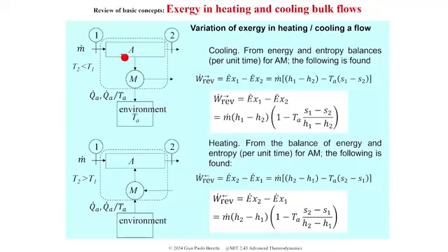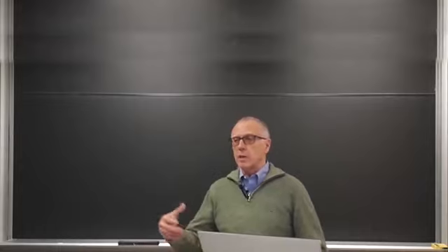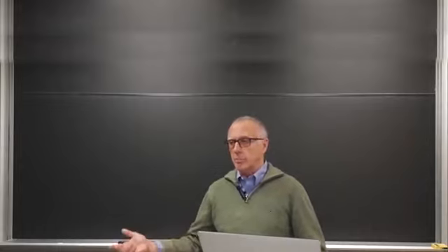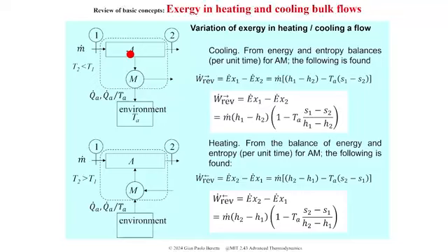It's not really a heat interaction, because the bulk flow typically changes in temperature along the pipe, or whatever pieces of equipment it flows through. So as it changes in temperature, if it experiences heat interactions, there are going to be many different heat interactions at different temperatures. But you could also represent this as an overall, or say an equivalent, heat interaction that would transfer the same amount of energy.